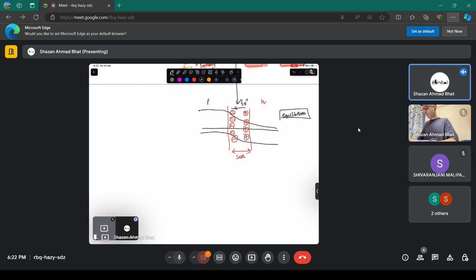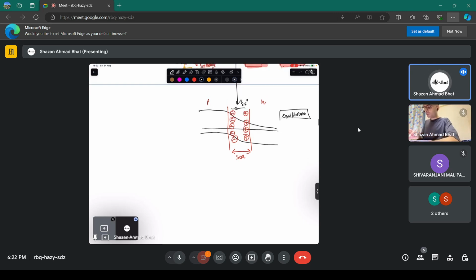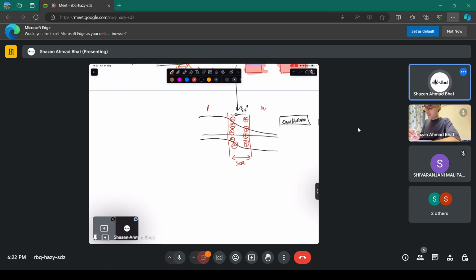Now, how do you make these things conduct? We studied in the last lecture that there's a distribution of electrons on this side. This is the distribution of electrons which comes from the Fermi function and the density of states. This is n(E), which comes from the multiplication of the Fermi function and the density of states. It's something like this, and then it exponentially drops.